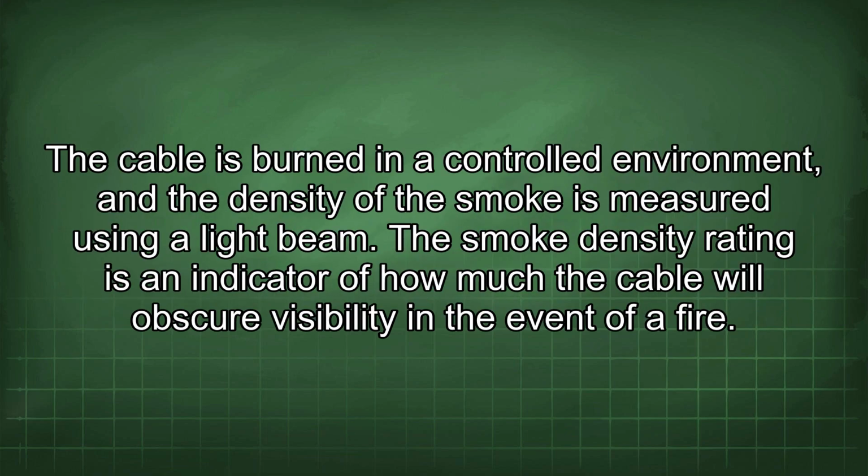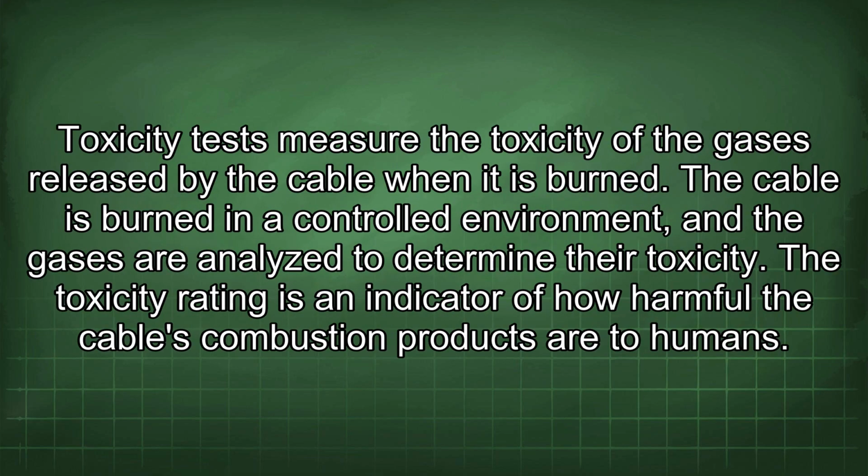The cable is burned in a controlled environment, and the density of the smoke is measured using a light beam. The smoke density rating is an indicator of how much the cable will obscure visibility in the event of a fire. Toxicity tests measure the toxicity of the gases released by the cable when it is burned.